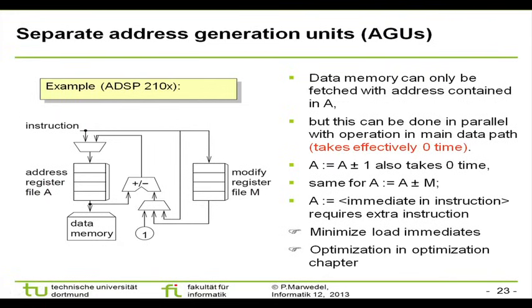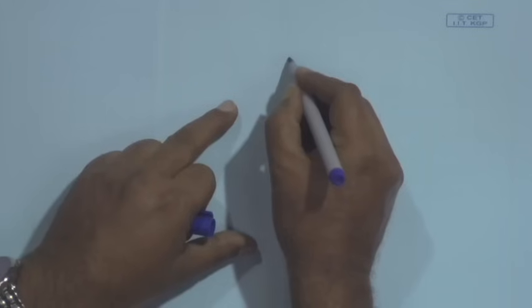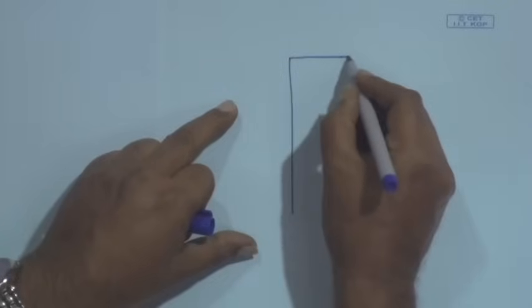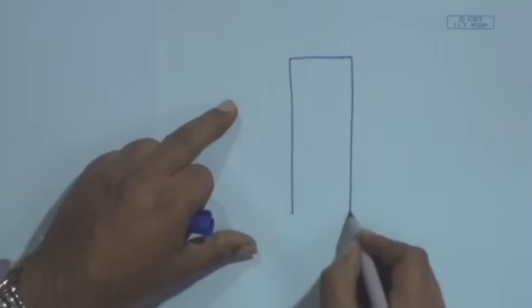What does it mean? It means I can work with 4 or 5 different arrays, and these address generation registers serve as the index of the register array. I will store all arrays. Arrays are a very important component of any DSP processing, and we will see later that we do not want linked lists to be used there.